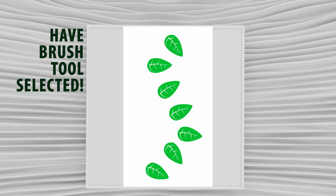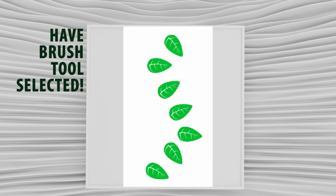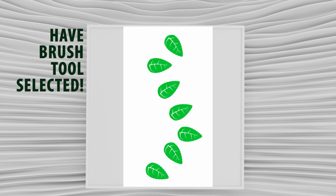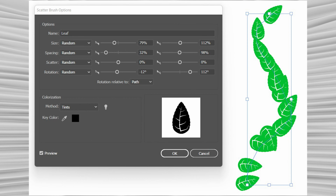All that's left is to test out your new brush. Draw a line of any type on your artboard to try out your new brush. You should see a scatter of little leaves along the line in a random pattern that you've drawn. Does it not look exactly how you pictured? You can still edit the settings.